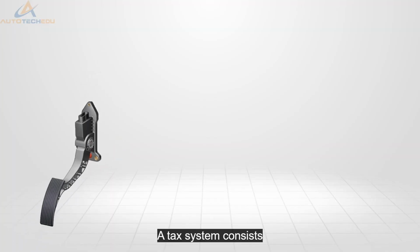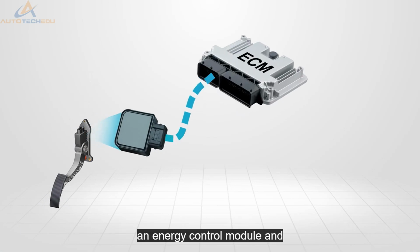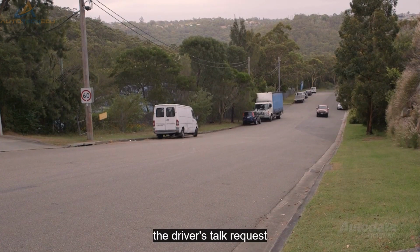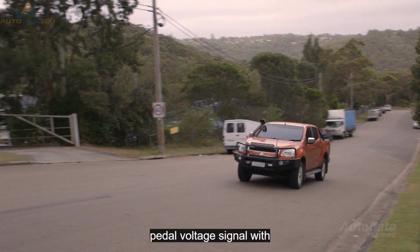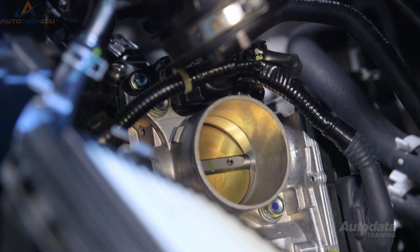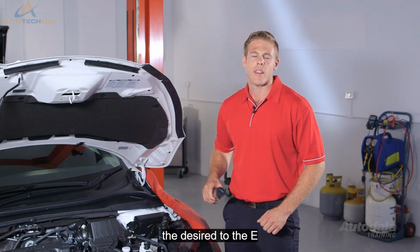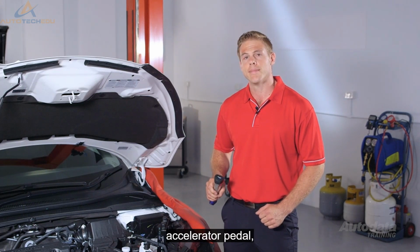A TAC system consists of an accelerator pedal, position sensors, an engine control module, and a throttle body assembly. The driver's torque request is communicated to the ECM via an accelerator pedal voltage signal. With this information processed, the ECM can command the throttle valve motor open or close, achieving the desired torque. The ECM can make adjustments to the throttle valve without the input from the accelerator pedal.